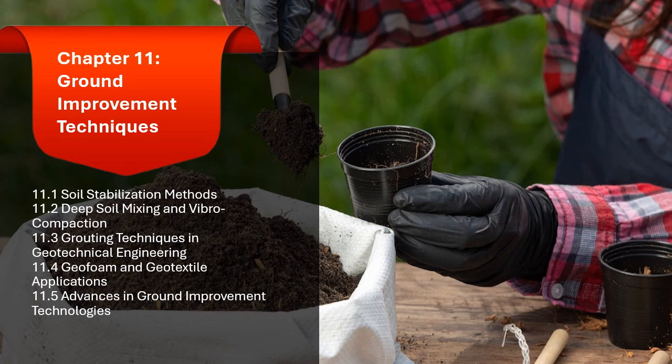1.2.2.1 Process of vibrocompaction. 1. Vibration probe. The process involves a large vibrating probe, often called a vibraflot, being lowered into the ground. The vibraflot produces intense vertical vibrations that penetrate deep into the soil. 2. Soil compaction.